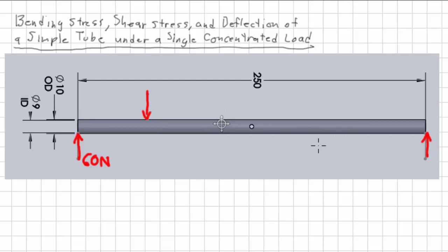This tube is going to be under bending, and we need to do a full analysis of how much stress. And there are two main kinds of stress in this situation. One is flexural stress or bending stress, and that's a normal stress. It goes perpendicular to the cross section. So often we're considering that as a cross section. The bending stress or flexural stress is normal to that, and so it will be denoted with sigma.